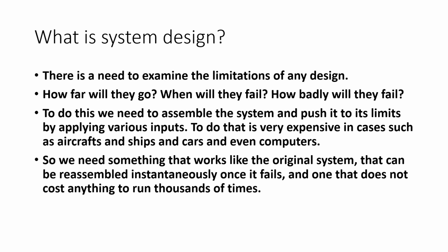So at that stage of design and probably the first level of manufacturing, there is a need to examine the limitations of any design. How far will they go? Will they satisfy the requirements of a design? For instance, a shaft may be designed to operate at 1500 RPM. So taking into consideration factor of safety and everything, you may want it to be safely operating at least up to 3000 RPM before it fails. So we need to know when things will start to fail, when they no longer operate within the requirements that have been set aside for them.